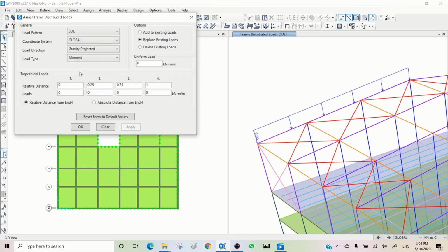So distributed moment. If you have such a distributed moment, in the local axis, generally moment is along the elements, so you need to use local axis. But in a specific case, if the moment in the result you receive from another consultant is in X and Y and Z direction exactly, you can put it in X and Y and Z.